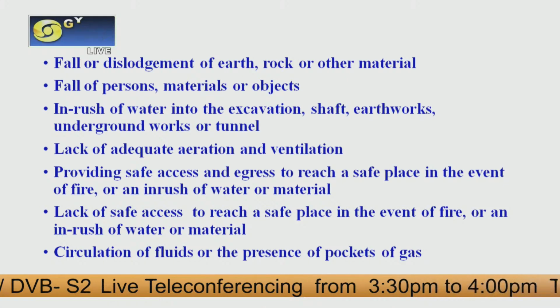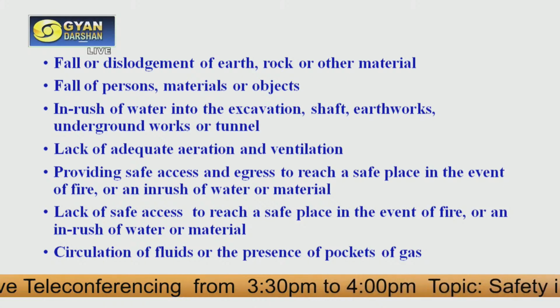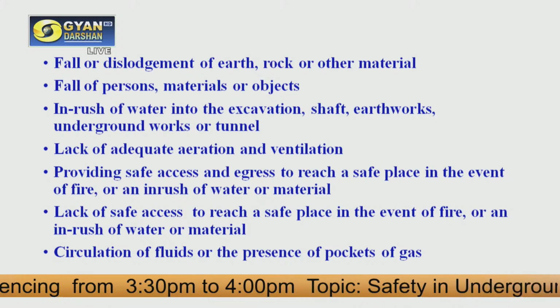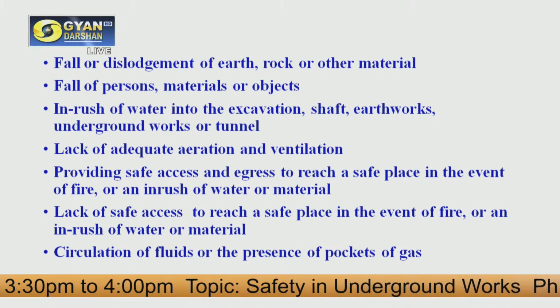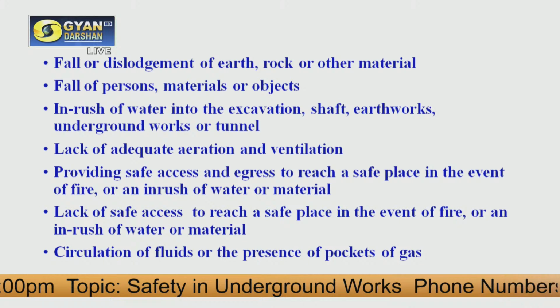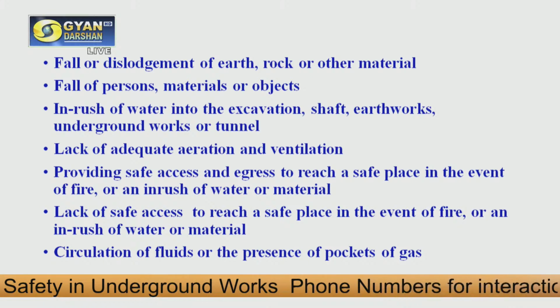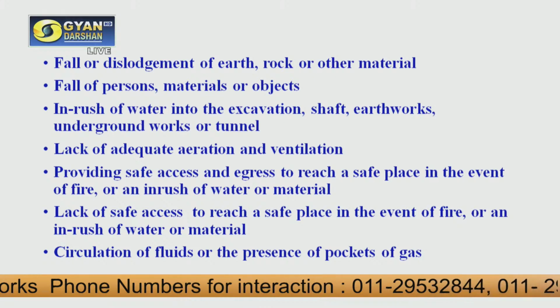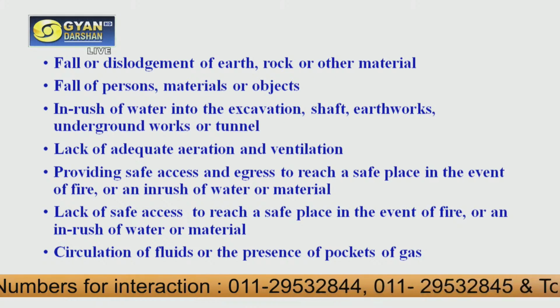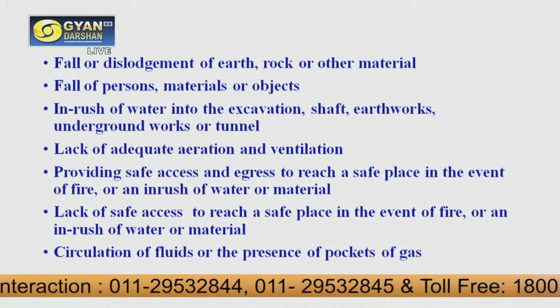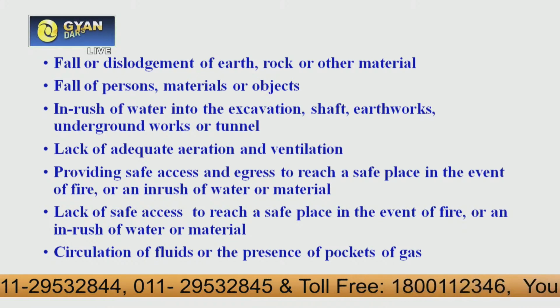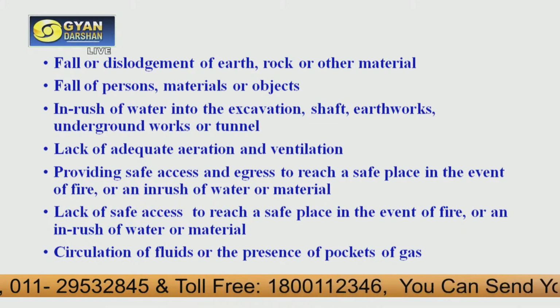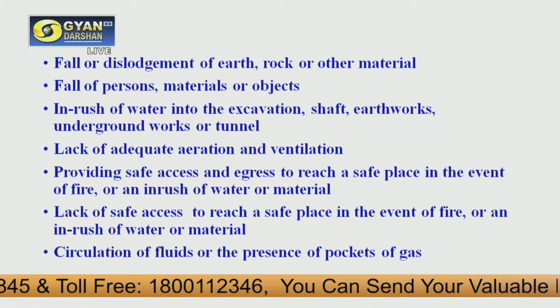So if that water pocket is hit, there will be an inrush or inflow of the water, or other fluids may also be there. This inrush of water into the excavation shaft, earthwork, underground work or the tunnel, if a lot of water is there, flooding may occur in that tunnel or trench, and workers may be trapped. This may also be the situation.